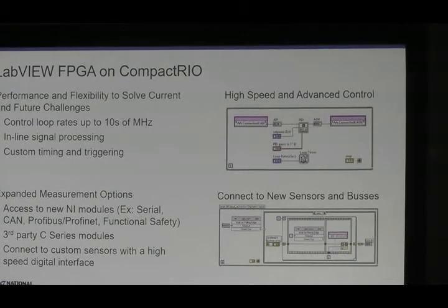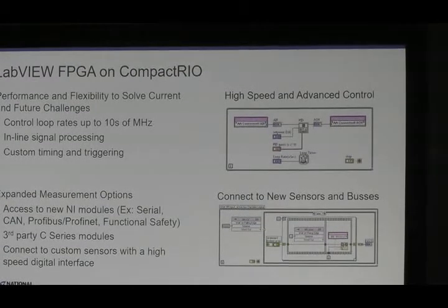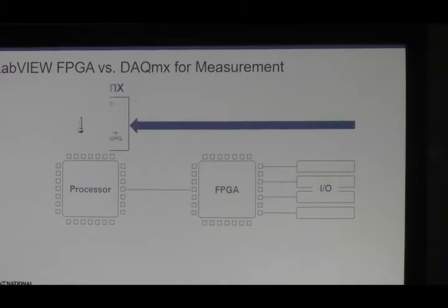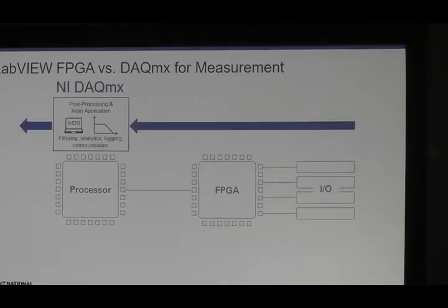And then, of course, with the high-speed digital capabilities of the FPGA, you can also do some custom interfaces. Switching from more of a technology view, looking at DAQmx and LabVIEW FPGA, to the application level, let's say a measurement application. If I'm going to use DAQmx, it's pretty straightforward. I'm going to use the API, the open, read, write, close method within NI DAQmx to get data into the processor, maybe do some post-processing there, and then send that data out to something, whether it's a laptop, server, cloud, whatever it may be.